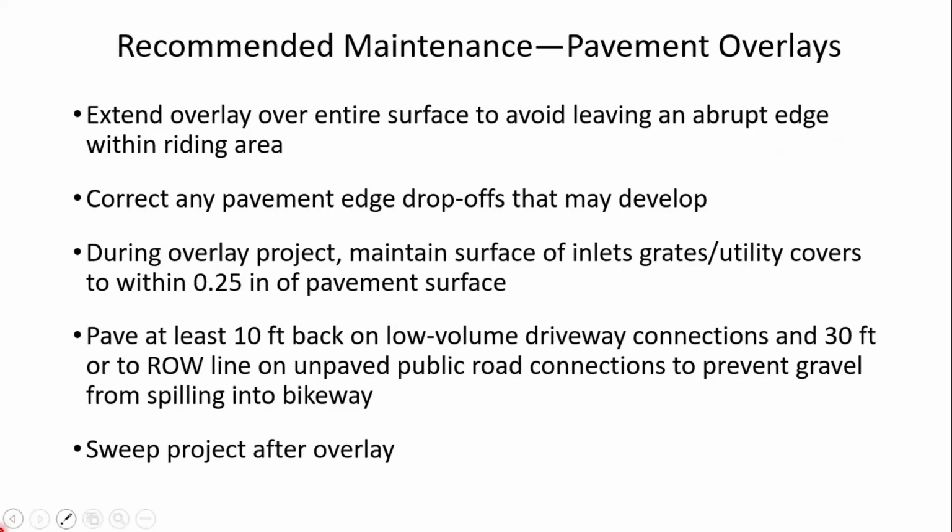Pavement overlays. Extend the overlay over the entire surface to avoid leaving an abrupt edge, that seam or edge within the riding area. Correct any edge of pavement drop-offs that may develop. During an overlay project, maintain the surface of inlet grates, I should say, and utility covers to within a 1/4 inch of the pavement surface.